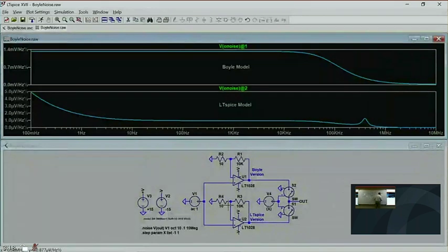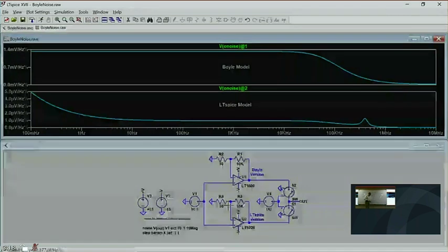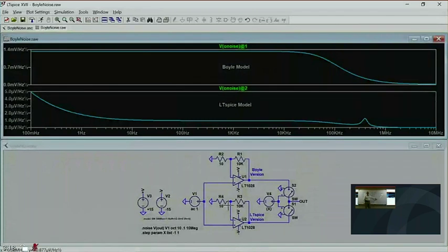And then you have circuitry to switch between input stages depending on the common mode current. And that's our op-amp, okay? Anyway, these diff pairs have different noise characteristics, and our models will look at how it's been biased to say which noise it should report.